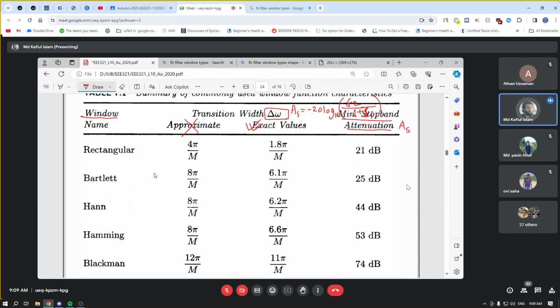Now remember, if you think about your frequency response characteristics, do you want your delta 2 to be higher or lower? Lower. So that is the ripple. You want the ripple to be as minimum as possible, right? You want delta 2 to be lower. Now from this formula, if your delta 2 is lower, what will be the value of your AS? It will actually become higher.